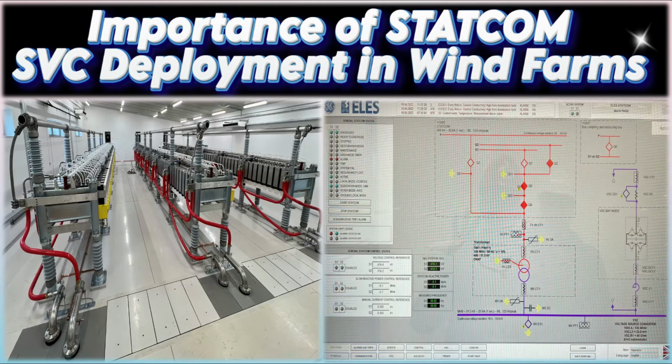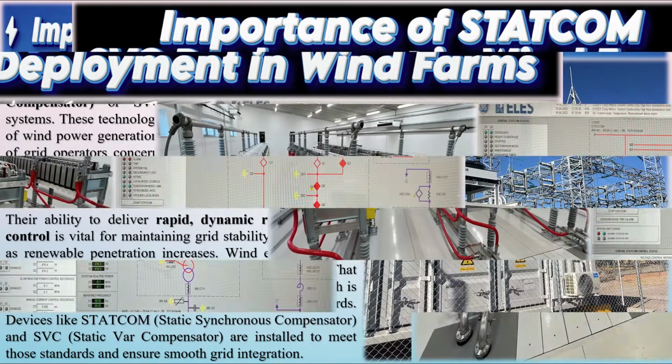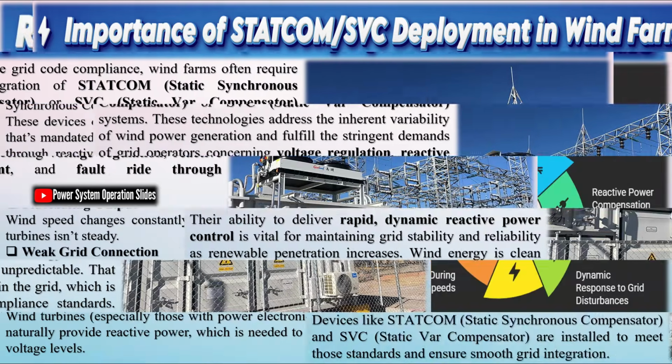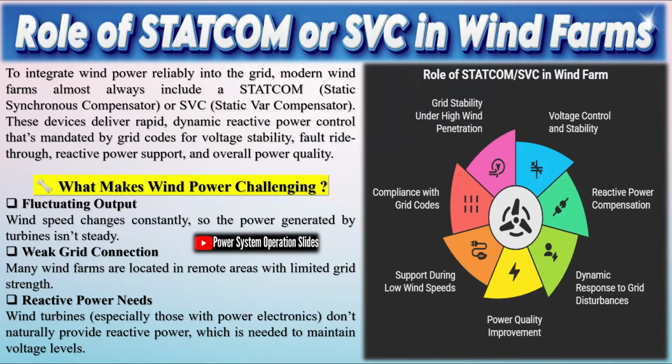Statcoms, also known as static synchronous condensers, have been a part of power system engineering since the early 1990s. Their topology and operating principles were documented as early as 1992, marking a significant evolution in reactive power management. These devices were developed to address the limitations of conventional reactive power solutions, both passive, such as mechanically switched capacitor banks (MSC) and reactors (MSR), and active, like thyristor switched capacitor banks (TSC) and reactors (TSR).